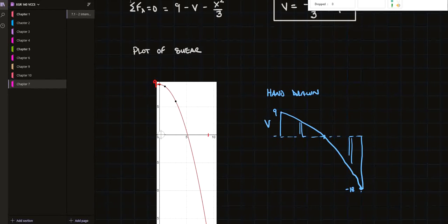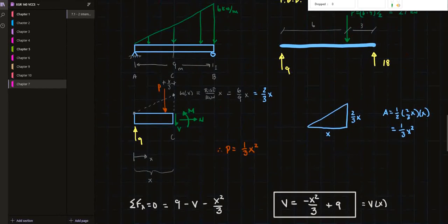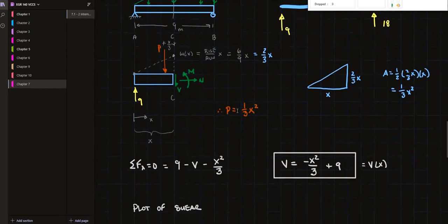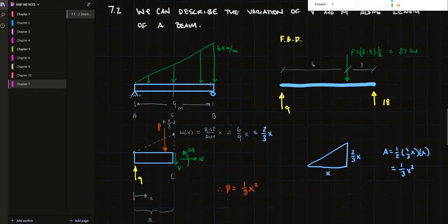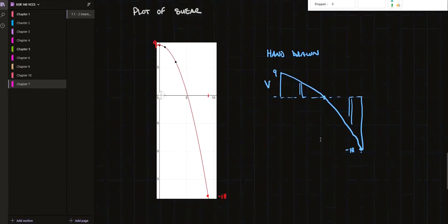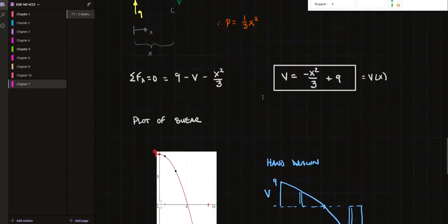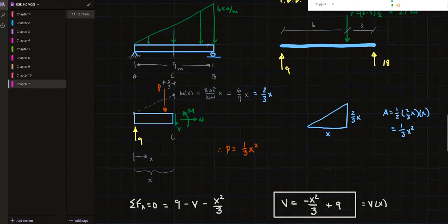And it represents the internal shear that is experienced in our member. And it makes sense. So there's more shear force here towards the roller bearing end, where the load is the highest, which means that if this beam was going to fail in shear, that's the highest point over here. It's going to fail over here on this edge.